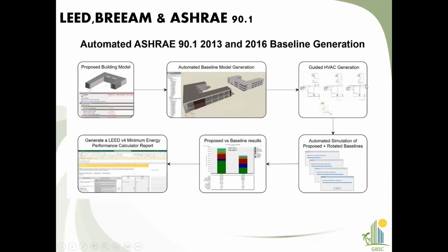And the basic controls and all the sizing parameters are already within that module in Design Builder. So we don't have to go into controls to that much extent, because as per the ASHRAE requirement, those controls are already inbuilt within the HVAC for the baseline. Then it will automate it for the proposed.